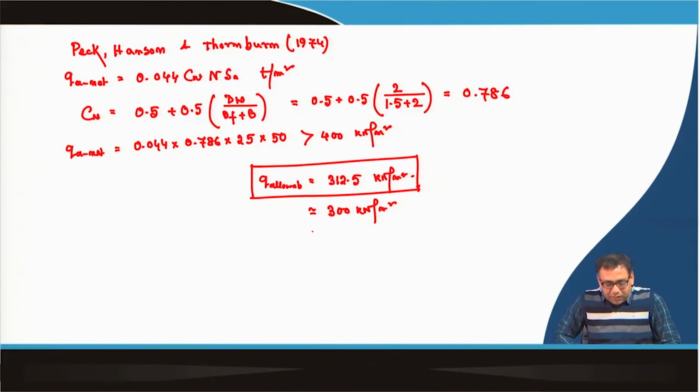Okay. And if you know the amount of load which is coming on the foundation, then you can check whether that load which is coming from the superstructure can be taken by this foundation or not. But here this load is not given. So, you can only propose the allowable bearing capacity of that foundation under this 2 by 2 cross section, and this is the value. Okay.